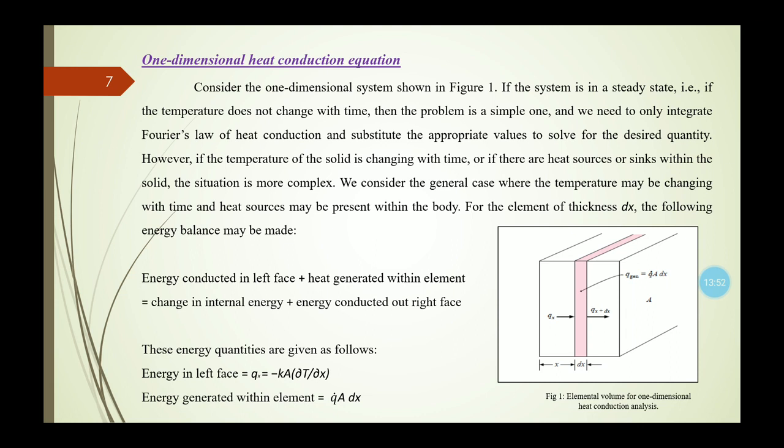So how do we write the equations for this energy balance? The energy in the left face, which is Qx, we can write from Fourier's law of heat conduction. So Qx equals minus KA del T del x. So we know this formula.